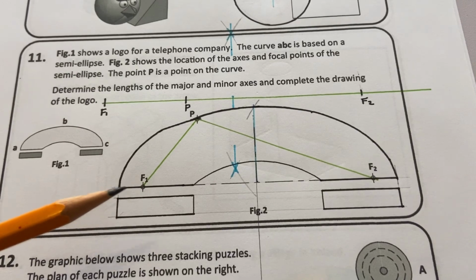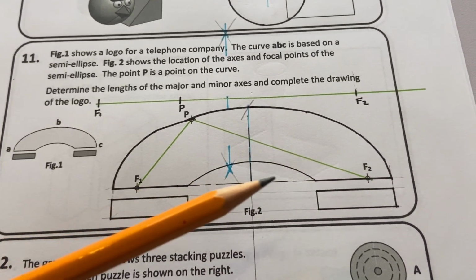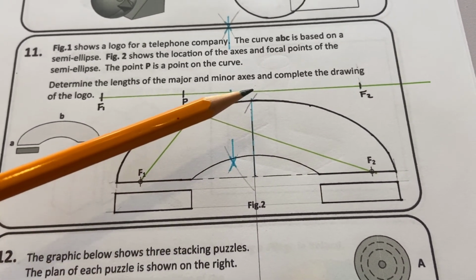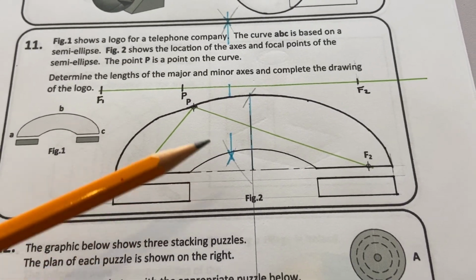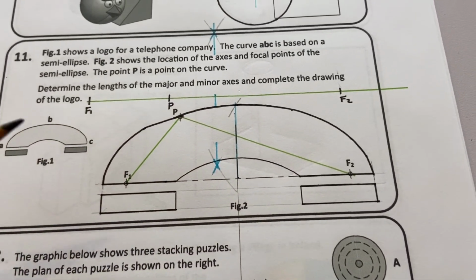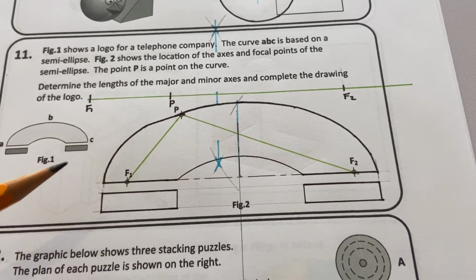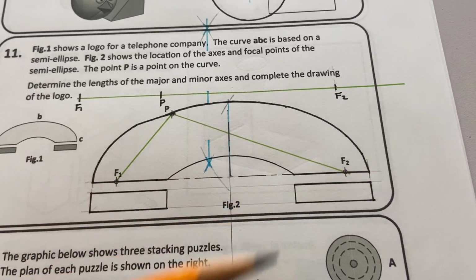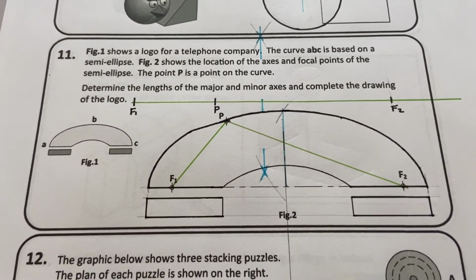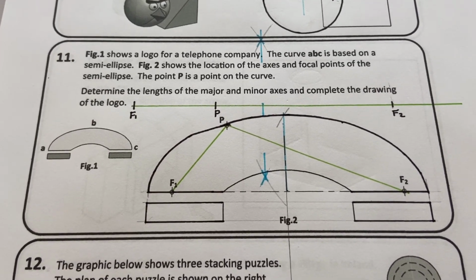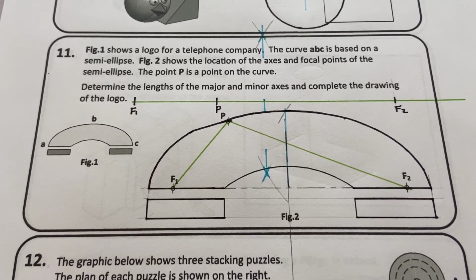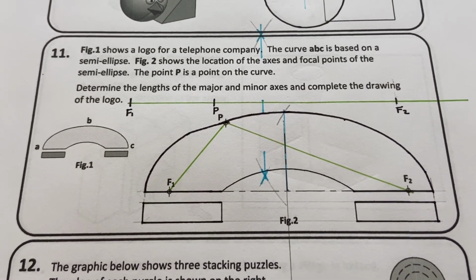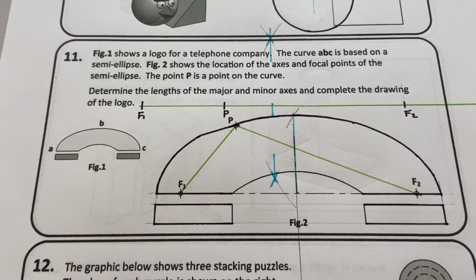Once you have that done, you have your full length of your major axis. Take half the major axis, put it on one of the focal points, swing an arc to locate the minor axis, then make a trammel or use the concentric circles method, and we produce the ellipse to fill up this space here. Then draw the two rectangles at the bottom, heavy in these lines here to complete the shape. A lot in that question requires a little bit of thought, but if you know your material, you shouldn't have any real problems with that. So that completes question 11.